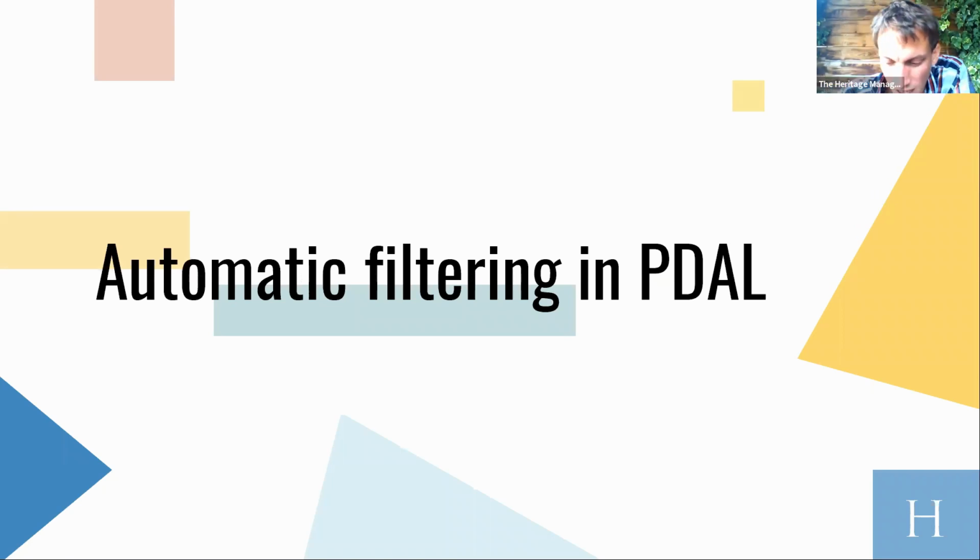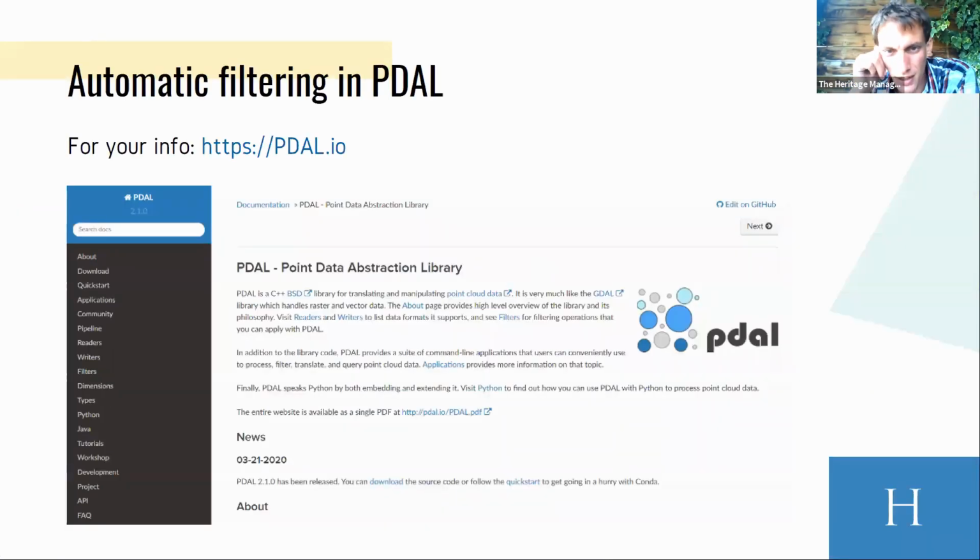Then the last thing is just for your information, the second to last thing, because I'm now thinking about something that I also want to show you, is filtering using PDAL. PDAL is something that we will not discuss too much in this presentation, but if you are a little bit into scripting, and if you are into GIS, you might or might not have seen PDAL. PDAL is an abbreviation of Point Data Abstraction Library, and it's actually a library of different tools that will allow you to do point cloud filtering, point cloud classification, and point analysis using scripts.